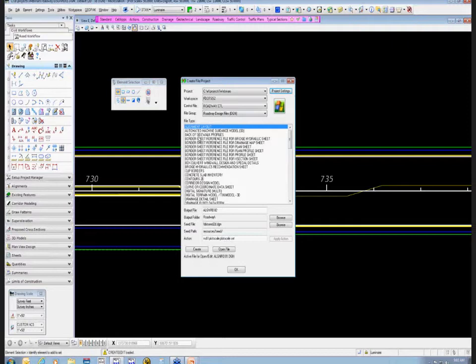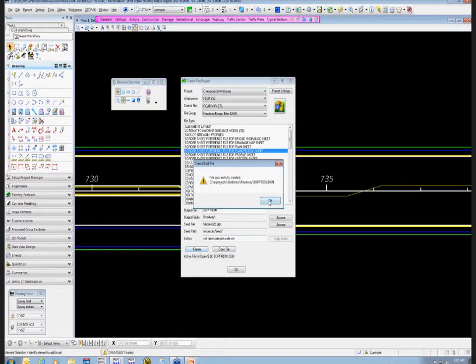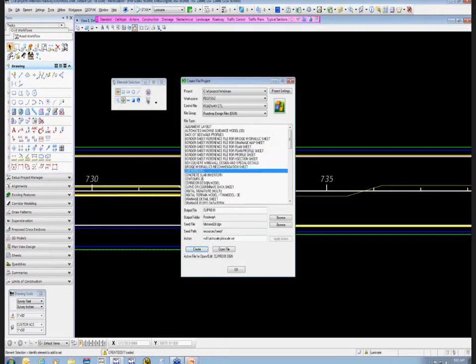And I want to pick out a couple of sheet files basically. First thing is that we're going to show you how to set it up using the borders. By default, if you use our sheet library, it's going to call to put it into this border file. So I'm going to go ahead and create the border file for plan sheets. Actually, I need plan and profile sheets. I'm going to create that. Clip borders. This is the file that we need in order to put our clip borders into. So I'm going to create that file,